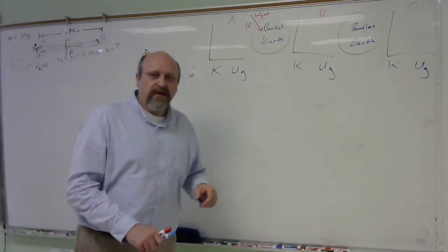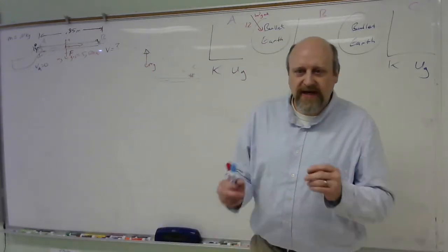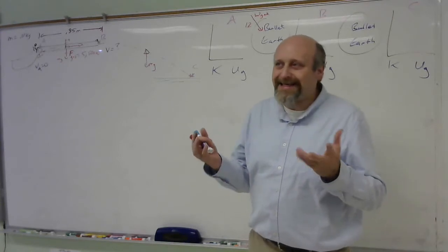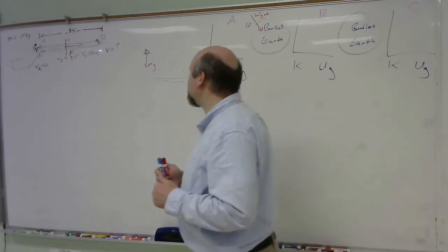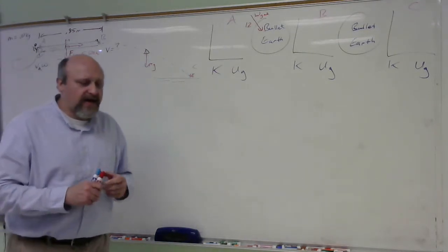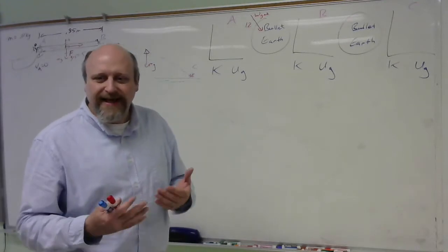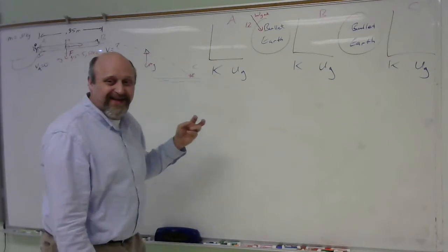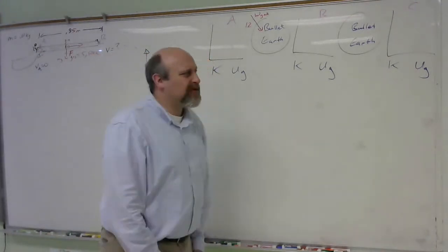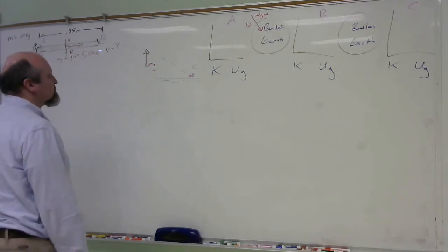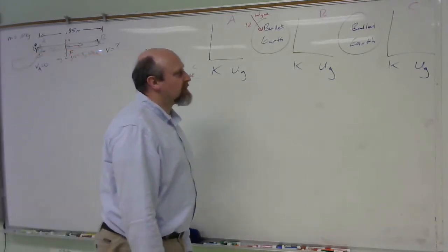Do I have thermal? And you say, well, yeah, that chemical reaction is going to heat up the barrel and stuff, but the barrel's not part of my system. It's going to heat up the bullet. Yeah, a little bit. It's not a whole lot of energy involved in that. I'm going to neglect that, I think. Thermal generally comes from friction and collisions, and they didn't give us really any data to work on to figure out that friction energy. So I'm kind of stuck. I'm just not going to include it, right? So I'm not going to include the thermal.